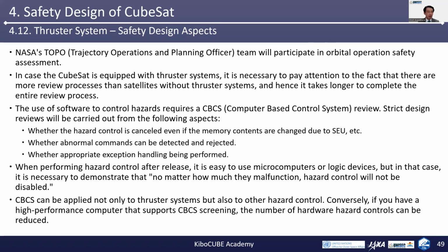The use of software to control hazards requires CBCS, computer-based control system review. Strict design reviews will be carried out from the following aspects. So whether the hazard control is cancelled if the memory contents are changed due to SEU, etc. Whether abnormal commands can be detected and rejected. Whether appropriate exception handling is being performed, and so on.